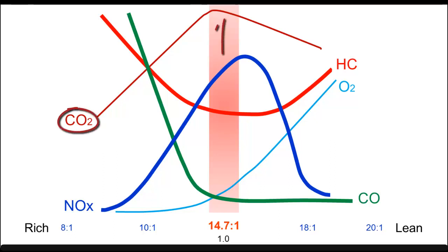In this case, carbon dioxide is at the highest reading yet at 14.67%, signaling stoichiometry, while oxygen is at the lowest reading yet of 0.21%. Remember, the catalytic converter uses some of the oxygen in the oxidation process. Lambda is at 1.01, almost perfect stoichiometry.